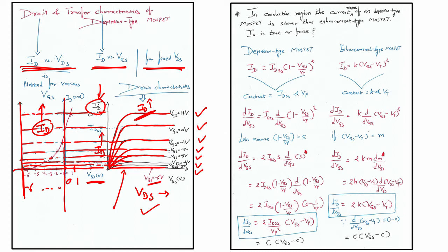Let us say VDS is constant. Let us consider minus 6. For minus 6, current is 0, so I will have 0. For minus 5, let us say current is 1, so I will put a star here, then 2, then 3, then 4, current becomes higher, still higher. For 0, and for 1 I can see my current is somewhere here, and let us say this value is 8 milliampere. Then I have points on this axis just by understanding the current value for a particular VGS value.